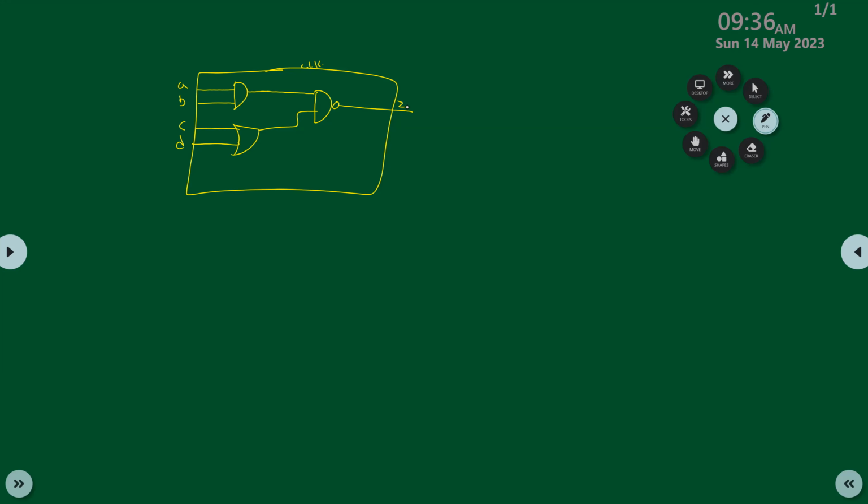So before writing any code in Verilog, first you need to identify the inputs and outputs. What are the inputs of the circuit? A, B, C, D. So in Verilog, each and every circuit we can call a module. Okay, so this is the syntax. Module is the main head of every circuit. So if you want to write anything, first you have to start with module and the module name.